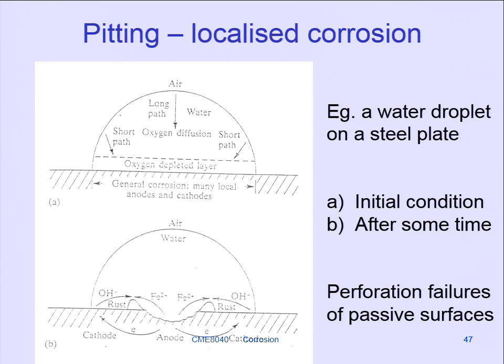And they are created depending on the reactivity of the surface. Little anodes forming at more reactive sites, cathodes forming at less reactive sites. And that relates to, as we've described before, slight differences in chemical composition across grains and the grain boundaries, and possibly differences in geometry. So surface roughness will have an effect on where anodes and cathodes form. So that's fine.